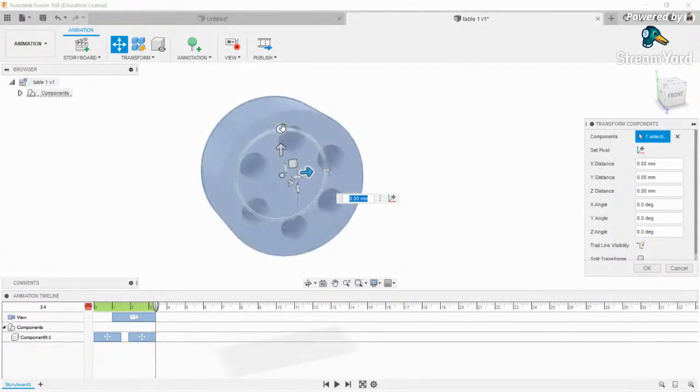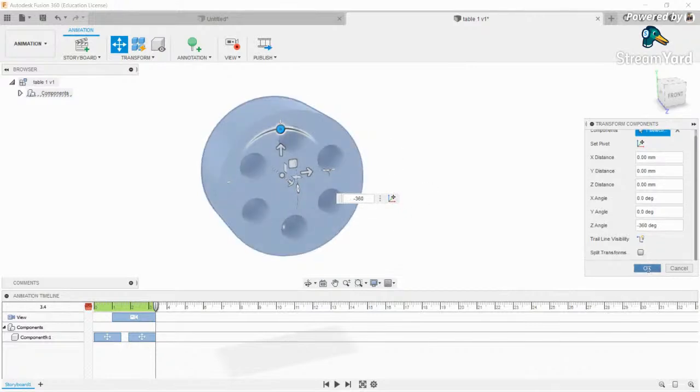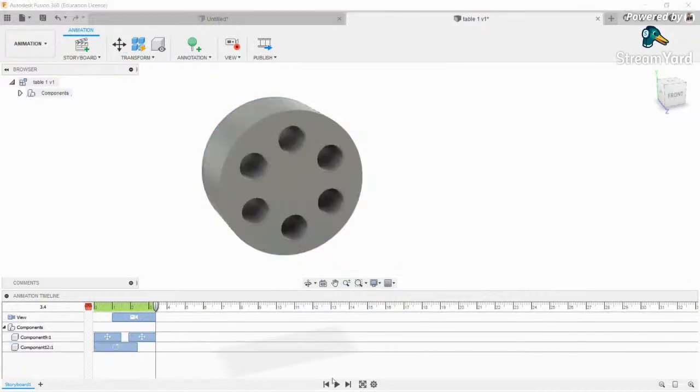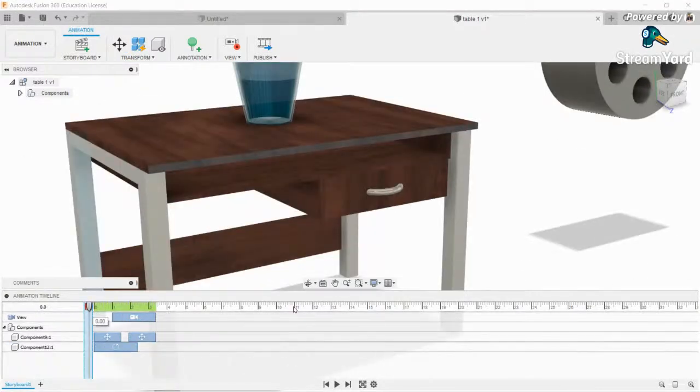So if now I want to rotate it 360 degrees, for that I'll choose this slider and rotate it. Now this option will come. There I'll give either minus 360 or 360. Both of them will work. 360 for one revolution, and 360 times 1000 or something like 5000 to rotate your model 360 degrees up to 1000 times. I'll not go for that. I'll just go for 360 only. So I'll press this and then play it.